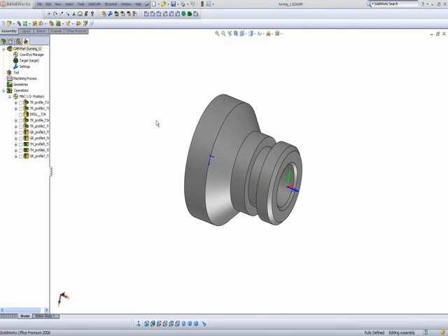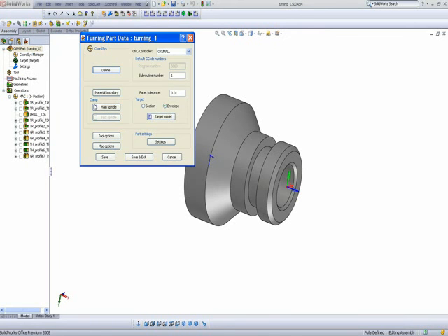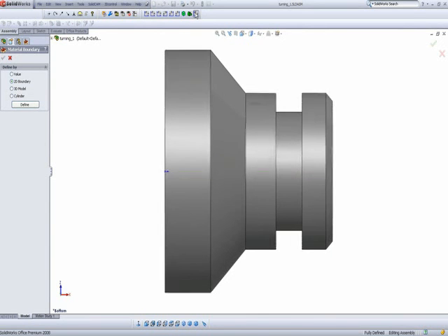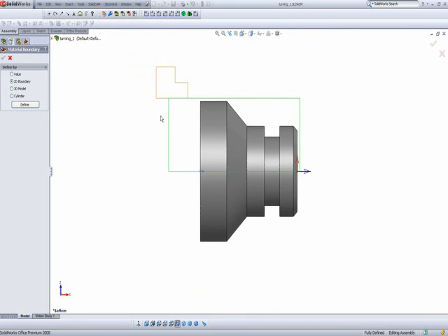Before I start machining the part, let's take a look at what I've done in my CAM part definition. I've created my home position, which is the center, as you see over here. My material boundary, I've created by creating a 2D boundary. To do that, I first have to have a sketch, which I've created beforehand. I have a sketch around the part.